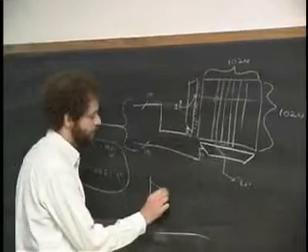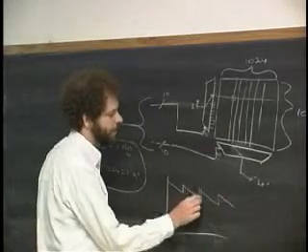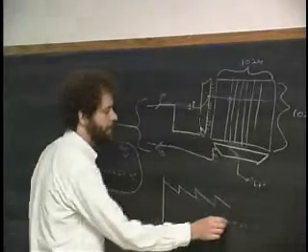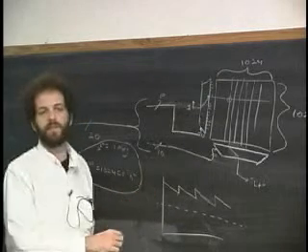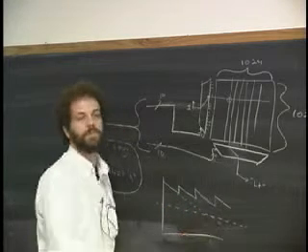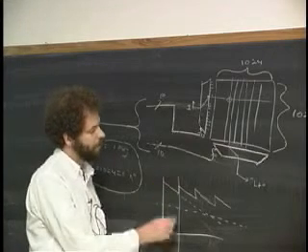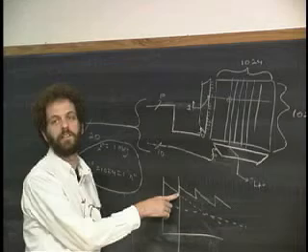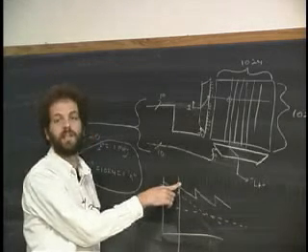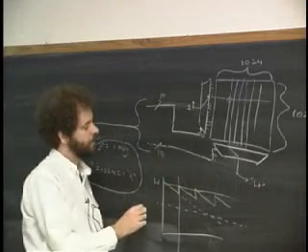So typically the charge inside of one of these capacitors, if it's being maintained at a high, kind of looks like this. So here's where we fill it up to, and then it leaks down. Fill it up, it leaks down. And here's the threshold that we use to determine is it a 1 or a 0. Now, if we're lazy, this will leak down past the threshold, and we won't know whether it was a 1 or a 0. But if every so often we go over to that thing and say, let me check to see whether you're high or low, and then I'll write back with higher quality than I was willing to accept when I read, and you write back a nice, strong, high voltage, then I'm okay.